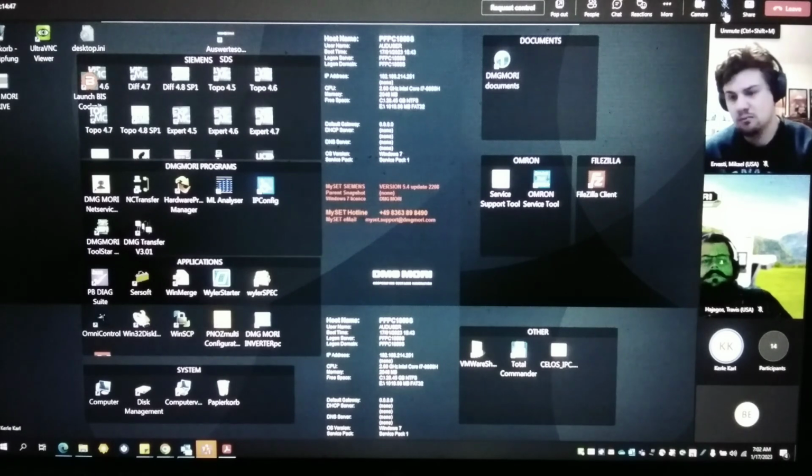Within the network card the function automatic sensing is included, and so the correct wiring, the correct wire assignment happens fully automatic, independent of which system you like to be connected to with your laptop, okay? And also independent of where it comes from, okay? So far, so good.